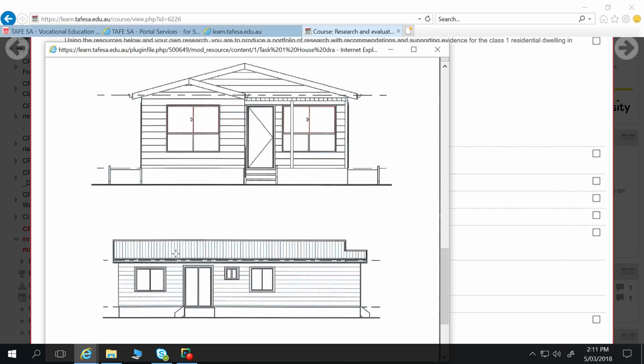So next time, if you're driving past Strathclyde South Road or so, you can have a quick look in there at their cold rolled steel section portal frame type sheds. That just refers to the independent frames. So if I do a cross section through a portal frame shed, so I've got in elevation, typically you've got your shed like this. Stratcos will do a maximum of 30-degree pitch on their shed roofs. That's about the max there.